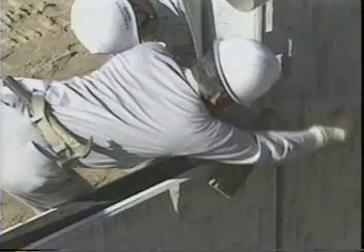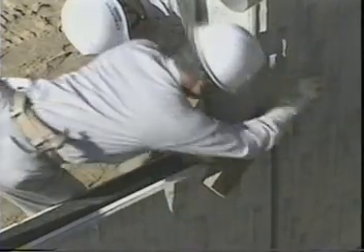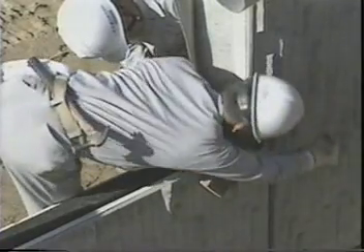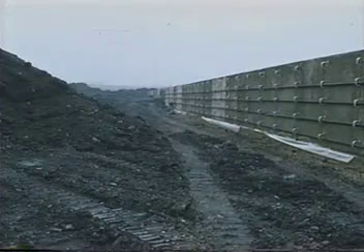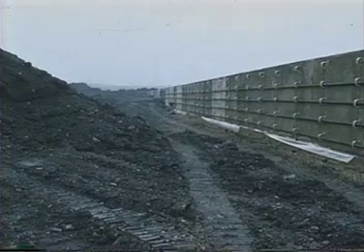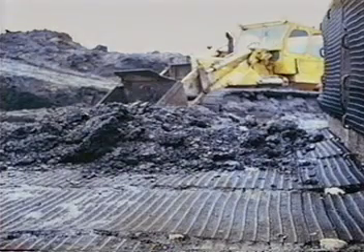For partial height panels, polymeric filler strips are placed on the horizontal joints of the facing panels. This allows several courses of facing panels to compress. Another alternative connection system allows the reinforcement to slide vertically relative to the facing panel.